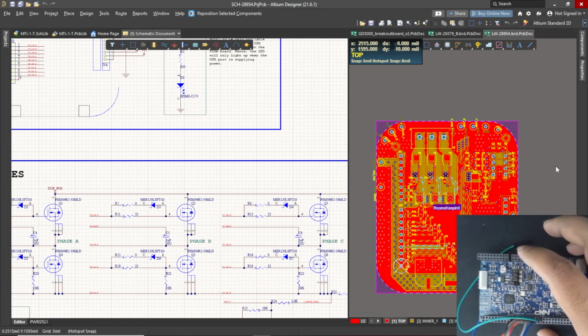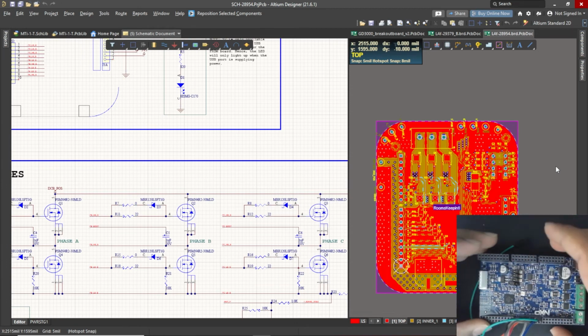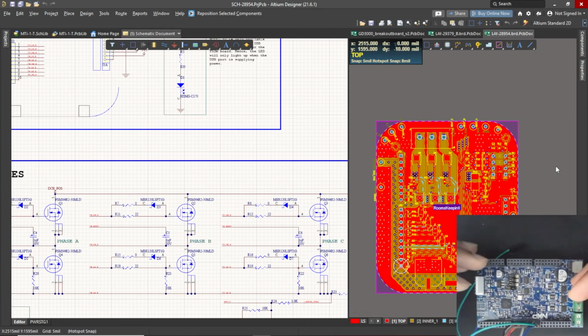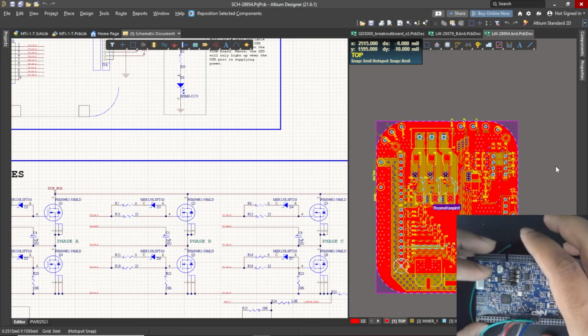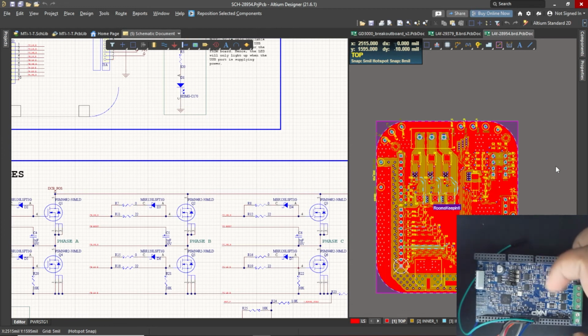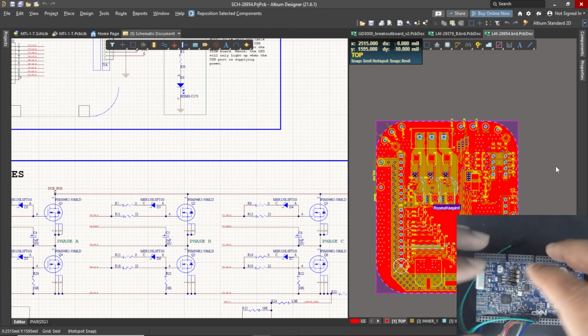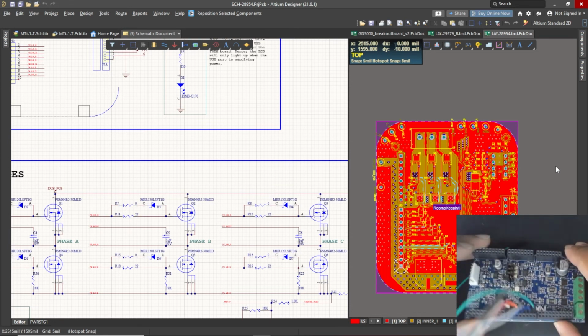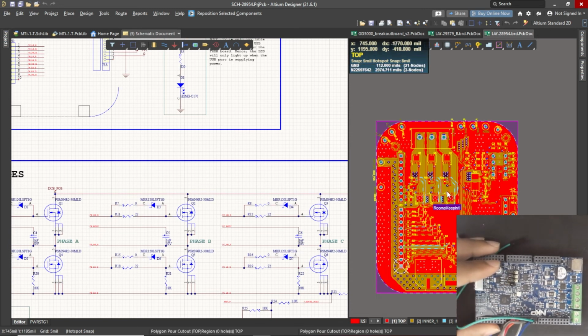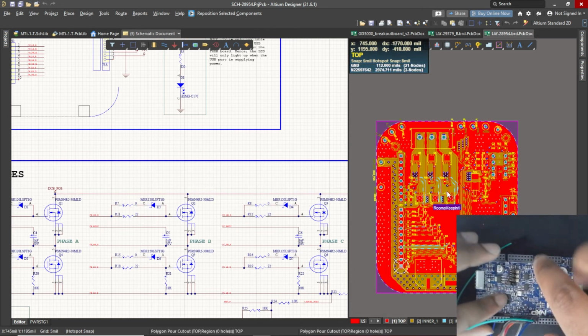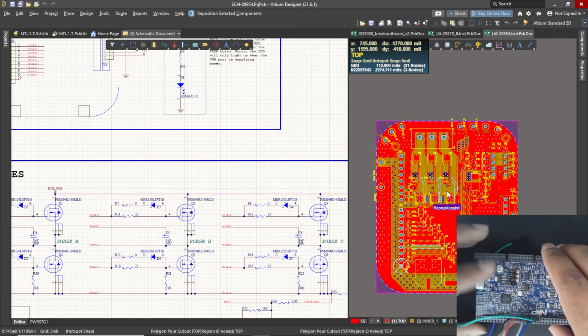But tomorrow, if I'm using a Texas Instruments pre-driver, or Infineon, or ST, it doesn't matter. This is just giving me the baseline, based on the component that I'm using, so that it makes the learning much easier. That's really it. I'm just mostly selecting PCB boards that are using this particular pre-driver, which is the NXP GD3000, for a brushless DC motor.